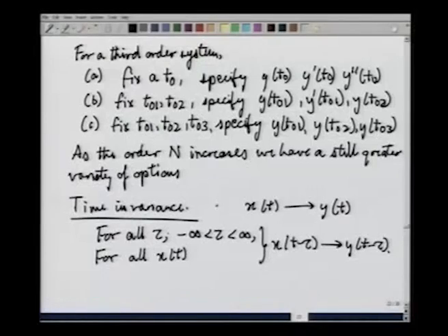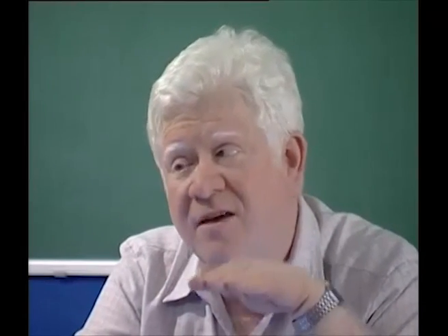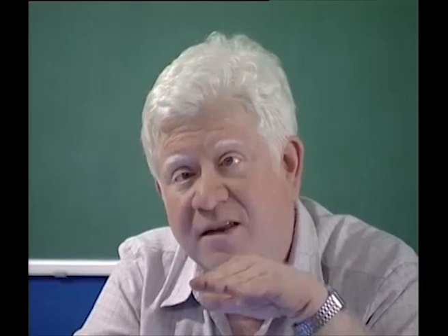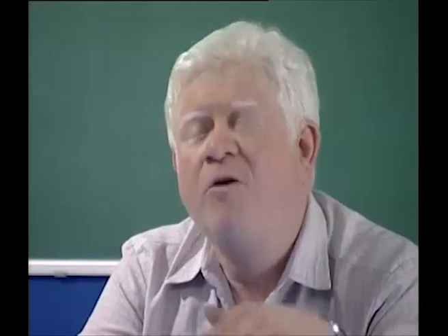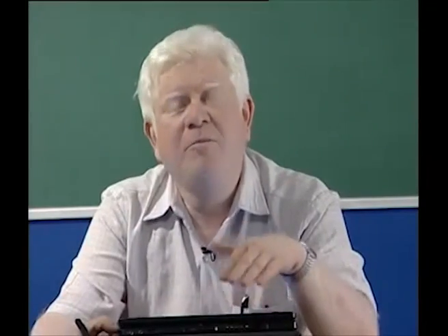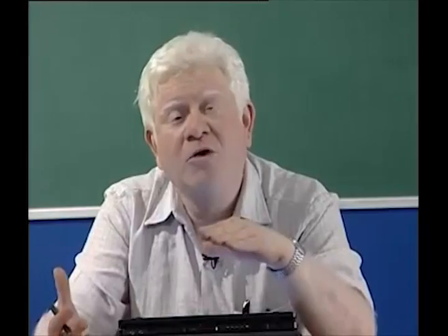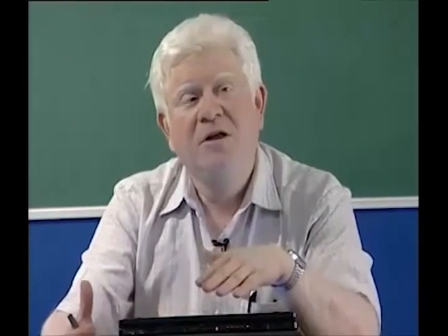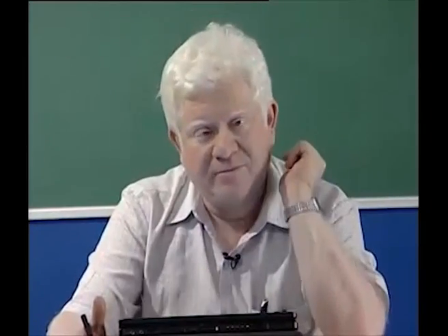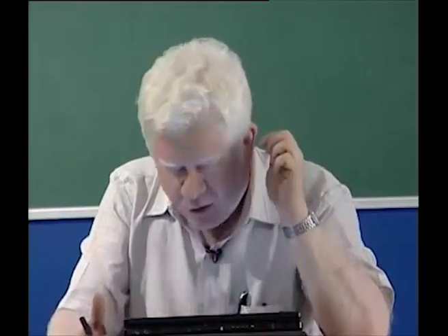Instead, you can just supply this rule over here and say that given this x(t), since we are going to get this y(t), for every other x(t) which is just a shifted version of this, we will simply get the correspondingly shifted version of the corresponding output. Hence, our lookup table would get a lot more compact, a lot simplified. So, this is the meaning of time invariance.